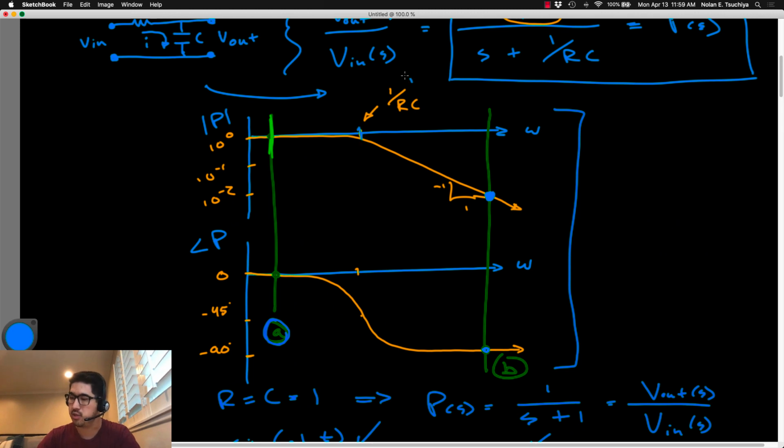By choosing R and C properly, you can decide where this cutoff frequency resides along the frequency spectrum. So you can choose to filter out really high signals and allow lots of low frequencies to pass through, or you can set it really low so that you only let really, really low frequencies through and sort of squash everything else above that frequency.